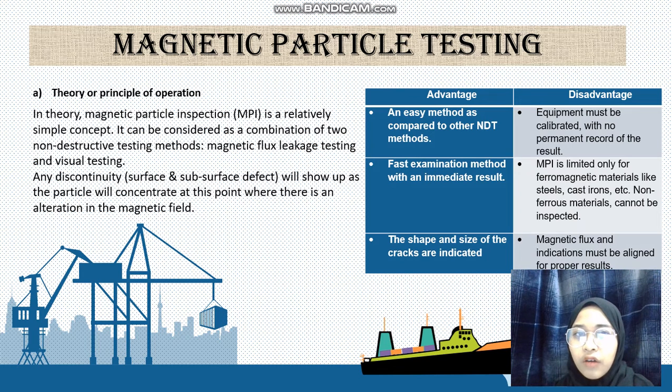The advantages of magnetic particle testing are, first, an easy method as compared to other NDT methods. Secondly, a fast examination method with an immediate result, so we don't have to wait. Thirdly, the shape and size of the cracks are indicated.